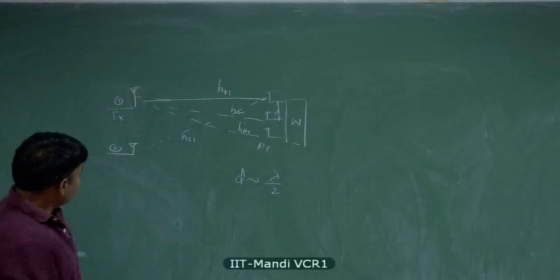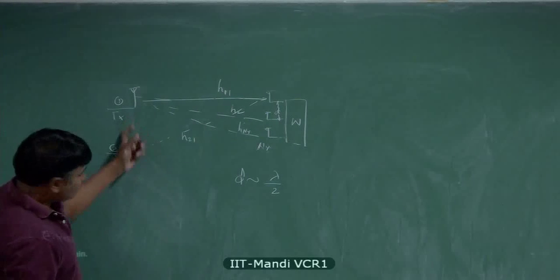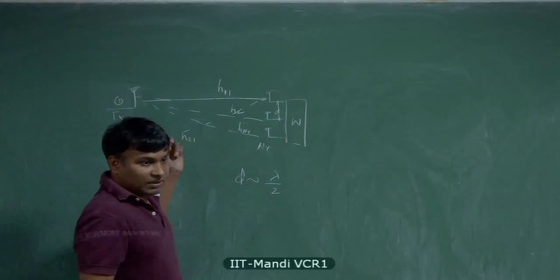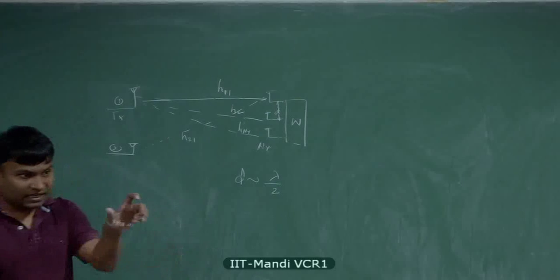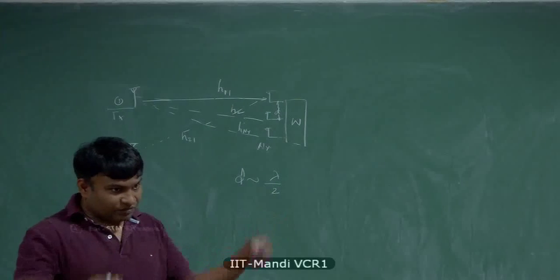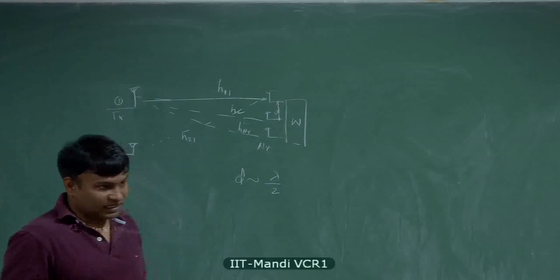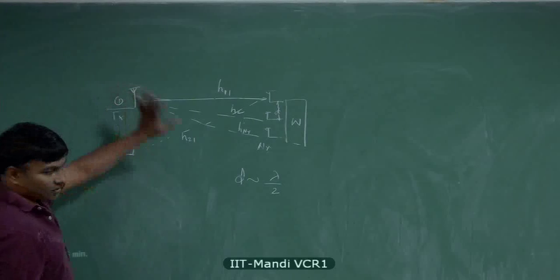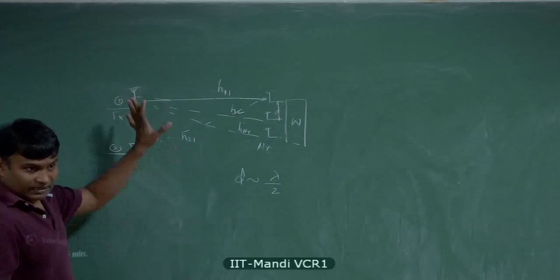But the distance between antennas at the base station should be a bit larger than this. Usually they are placed like 10 lambda apart. If you see the antennas on a base station, on a cell site, you see that they are placed a few meters apart, if you ever observed it. Of course, for each antenna we are assuming an omnidirectional radiation pattern here.